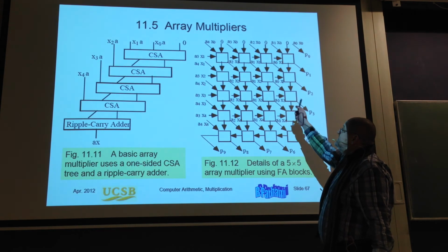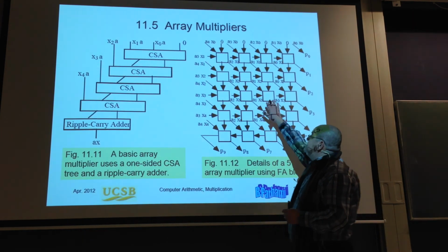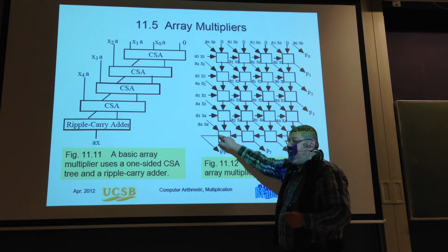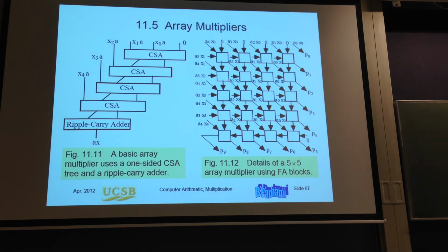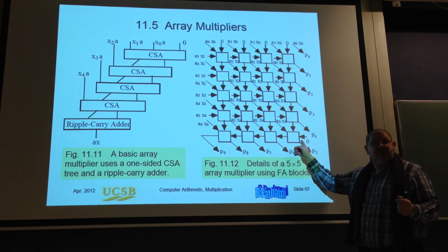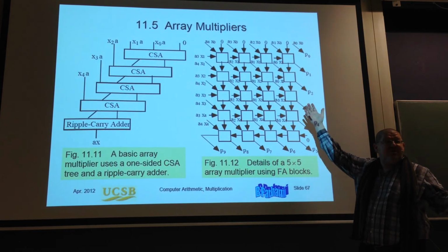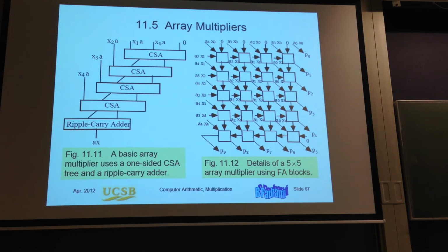And this will result in such a structure. Then in here, those are the reduction parts, and here this is the ripple carry adder part. This is a very slow design if you compare with a normal tree. Because I'm not using here a fast adder, I'm not using here a tree. It's a degenerated tree, it's linear. Now, why do you think somebody had such an idea?